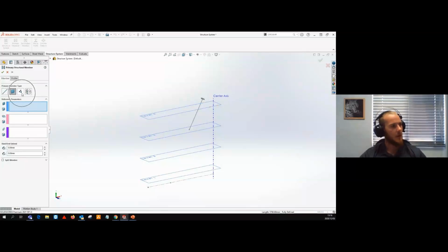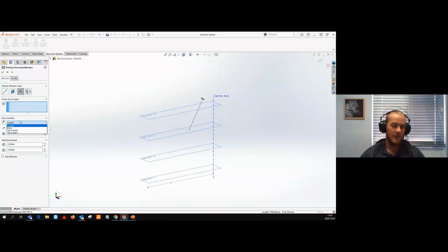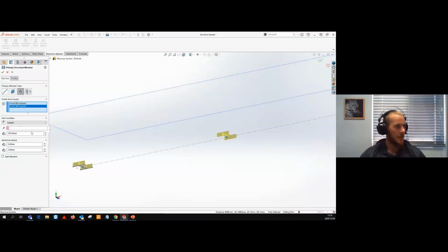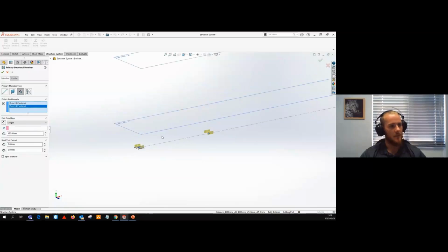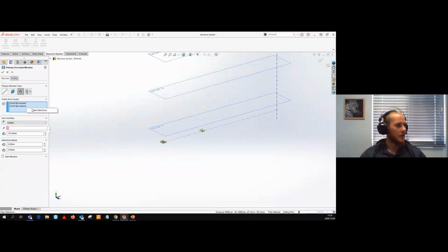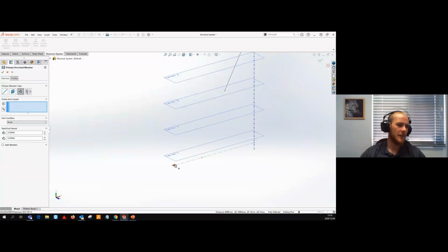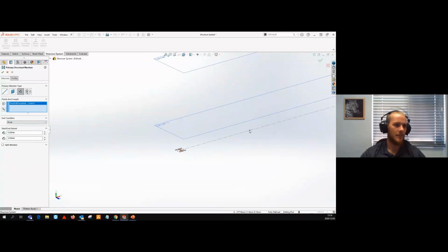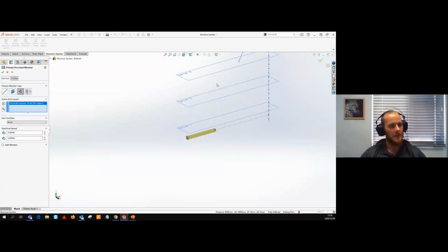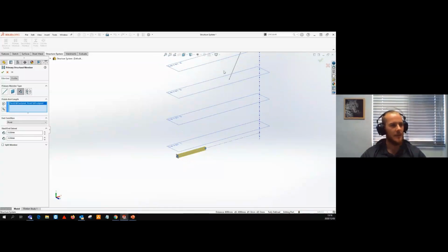The point option is quite powerful in the sense that there are quite a couple of end conditions that go with this feature. As you guys can see, for example, I will be selecting these 2 points over here, and you'll notice the software being able to add an actual distance on those points, using them as positioning. Moving over to the normal point option, if I just select these 2 sketch points, it basically creates the members between the selected points.